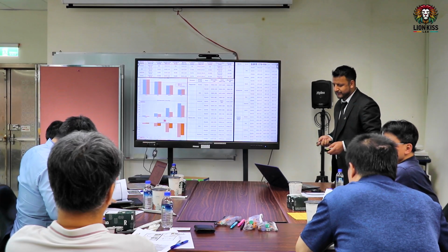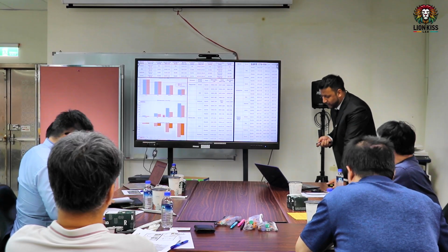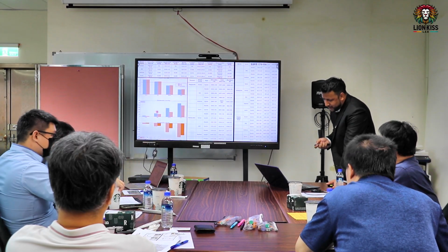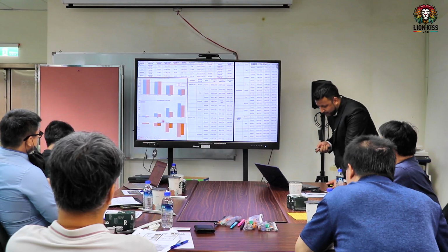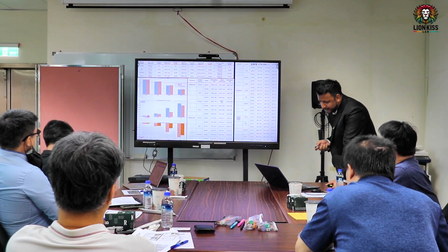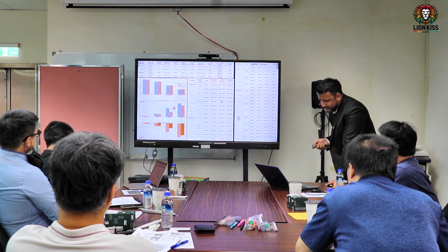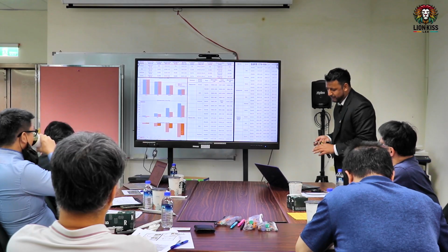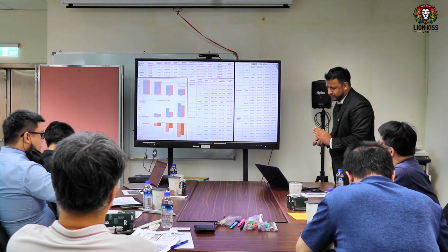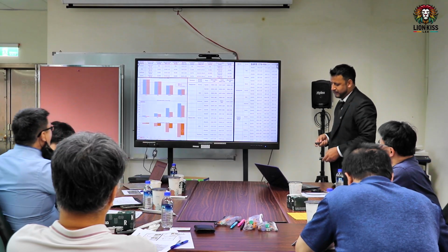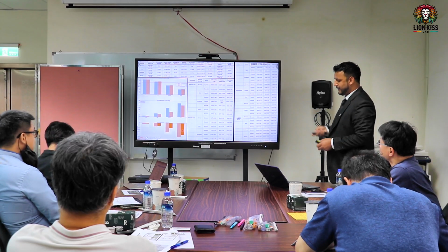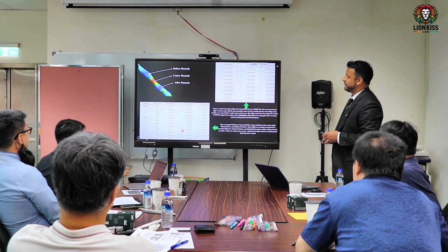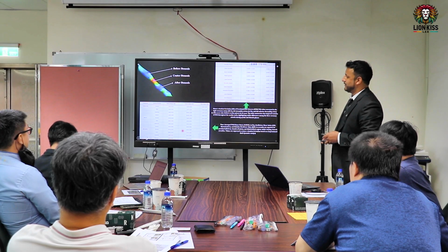And the wall shear stress gradient, before stenosis and at the center of stenosis. So we compare between the systolic and diastolic. The wall shear stress gradient is increased at the center, and after stenosis the value is decreasing from the center of stenosis, and the gradient decreases with increasing level of stenosis. So we measure that value before stenosis, center of stenosis, and after stenosis.